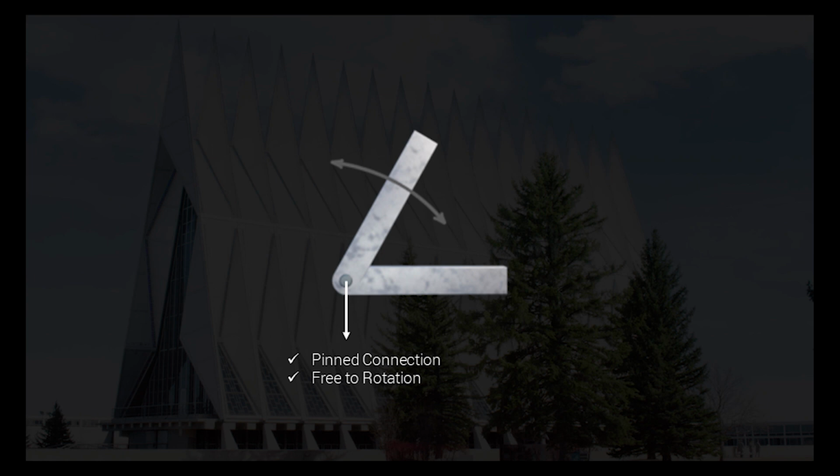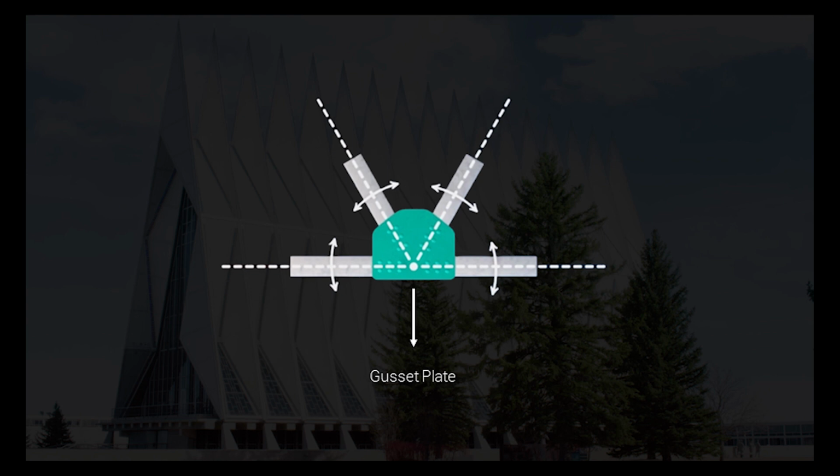There are two important assumptions we need to be able to make for a structure to be considered as a truss. First, we need to be able to assume that all the joints in that structure can be represented by a pinned connection, meaning that the members are free to rotate at the joints. The members of a truss are often rigidly connected using what is known as a gusset plate. But if the center lines of all the members at the joint intersect at the same point, like they do here, it's reasonable to assume that the joint behaves like a pinned connection.